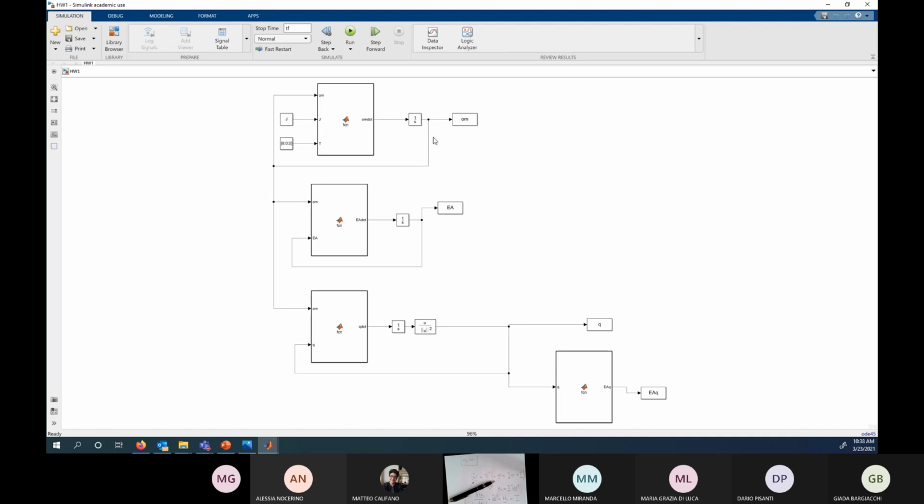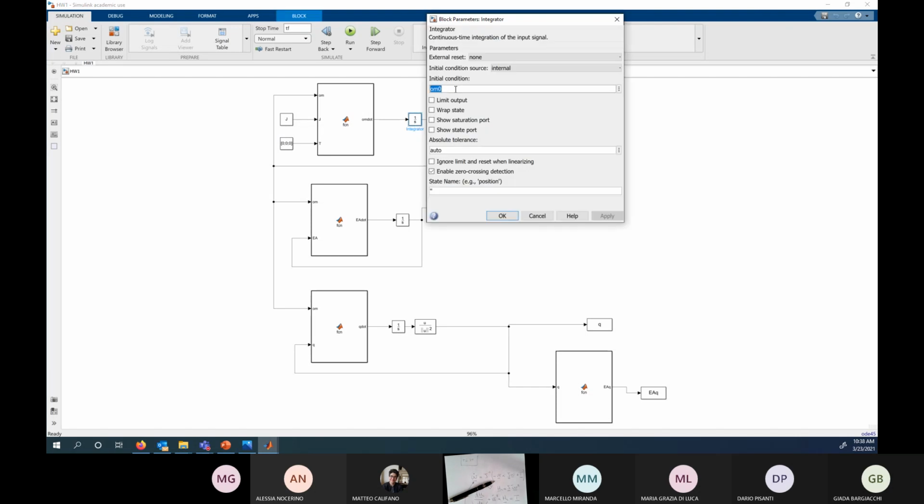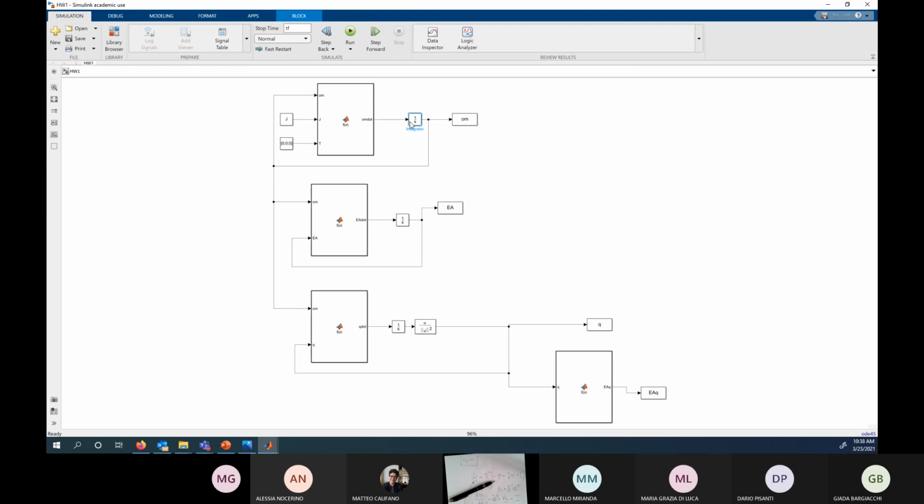The omega dot allows me to take the block in Simulink that is called numerical integrator, 1 over S. I specify here an initial condition. I called it OM0. I'll show you what those are defined as in a second. And numerical integration of omega dot gives me what? It gives me omega. And so I feed that back into the block itself. So this is how a numerical integration really occurs in Simulink. Forget about these other blocks, but really they're doing the same thing. They are integrating different differential equations. This one is integrating Euler's second law, given some initial conditions that I'll show you in a second.